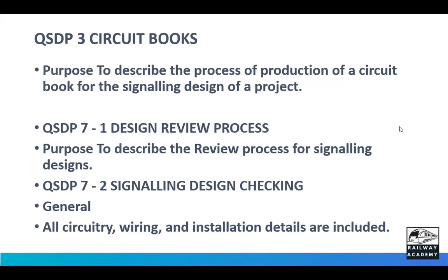So you have got another standard, number 7, the design review process. Suppose you have done the design, like in the UK, you will be doing your production checking, your own checking of design. Then you will give it to the checker, who will do the checking. So before you give it to the checker, you do your own review. How do you do your own production checking, your own review? They call it the designer's review.